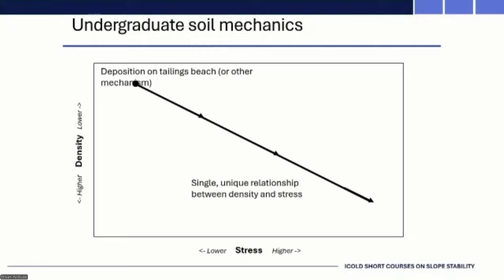Maybe you get some bleed water, which means the void ratio decreases initially, but then it has to decrease further, either through additional loading, through drainage, the loss of water, that's probably a small component, or you can get this desiccation effect due to the drying effect of the sun. That's like applying an additional stress, which drives you further down that diagonal line that I've shown there.